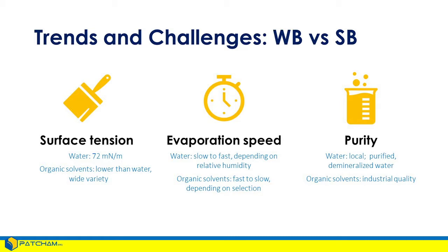And we're going to discuss the requirement why, but just keep in mind that in order for a liquid to wet a substrate, the surface tension of that liquid must be equal to or lower than that of the substrate. That's the only way it will spread. If not, it will sit as a droplet on top of the substrate. In the worst case, as a droplet sphere. As an example, a very high surface tension liquid that we're all familiar with is mercury. Mercury in its free form, sitting on, let's say, a steel substrate, exists pretty much like a ball. It rolls around because it's so high in surface tension. That's why it won't wet that substrate.